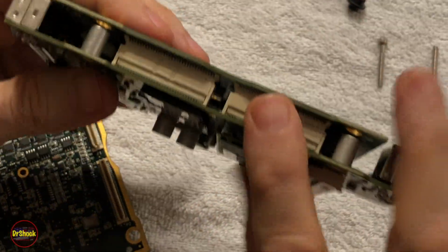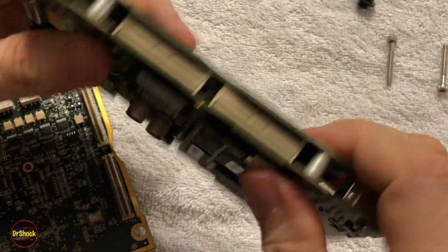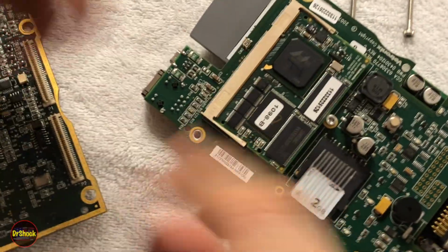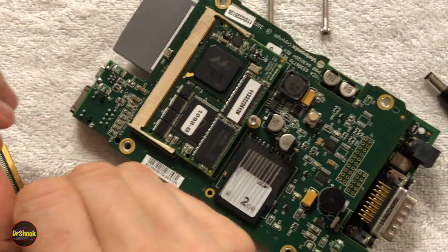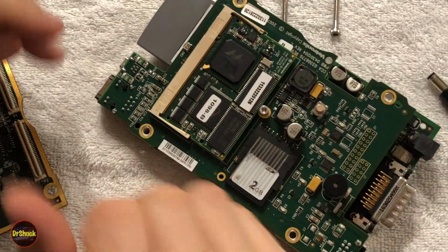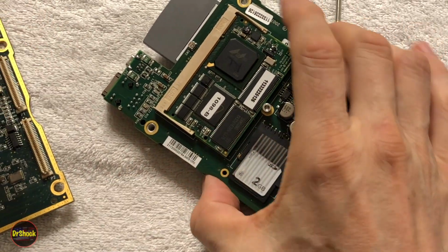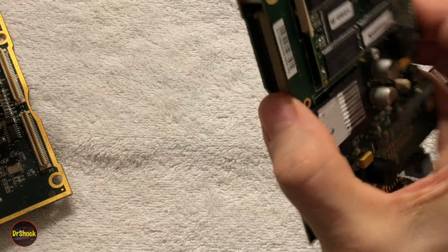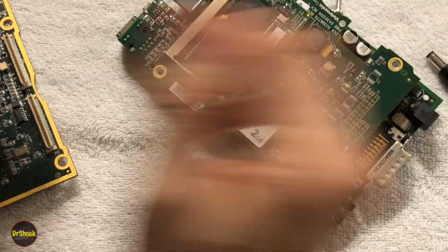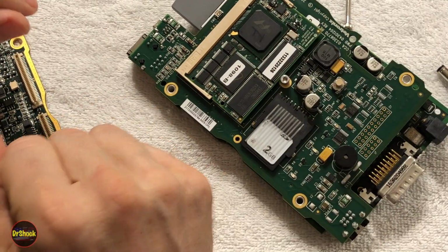There might be something about that makes them incompatible. Although it's electrically compatible and gets through the post-test, it may not be compatible for running through all the vehicle operations. And you might not be able to practically test all that. It might only fail specific types of vehicles and specific operations in SPS2 or specific operations in GDS2 that it would be just too cost prohibitive to exhaustively test. But it might be good enough for the customer who's asking you to fix this to do something like that. So I hope that helps you out.